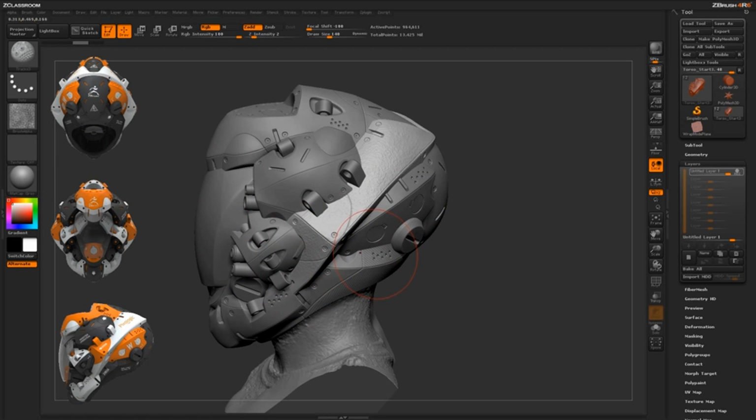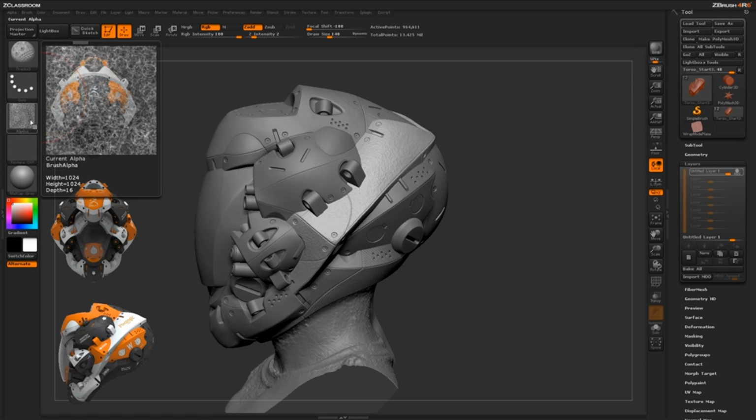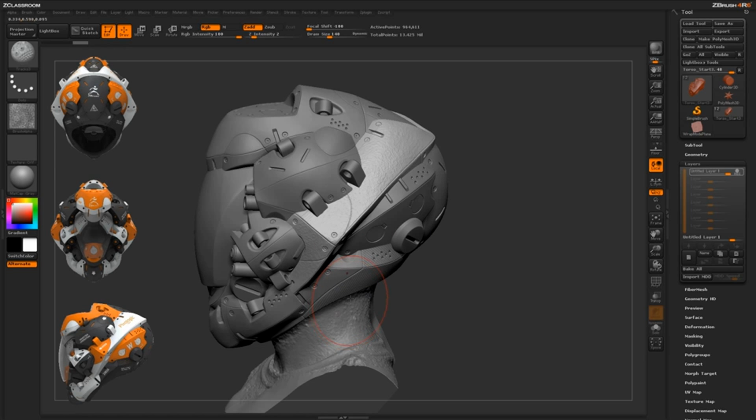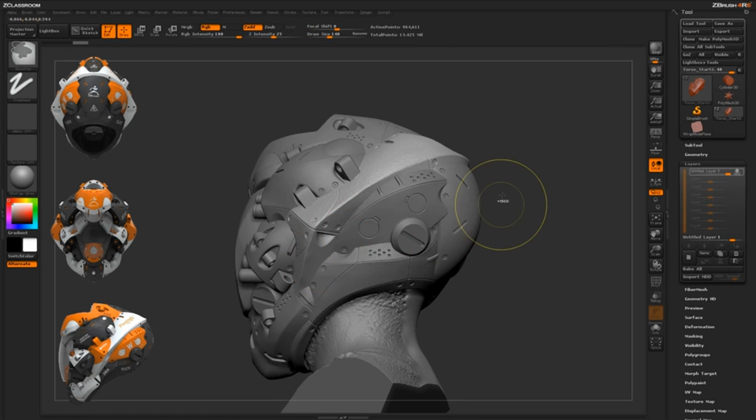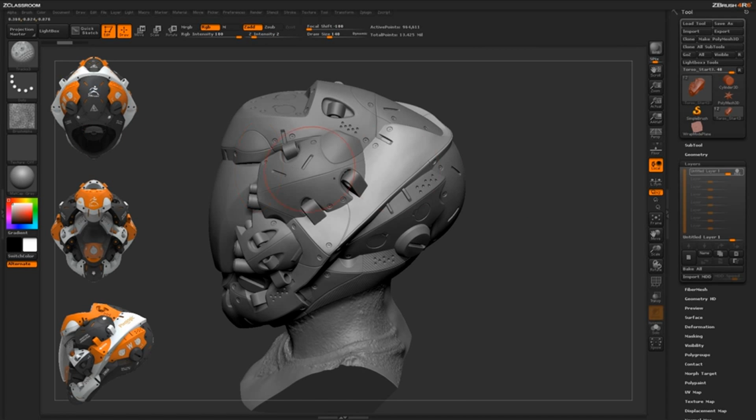So this process here is great for using on straps or other really skinny elements that you may have on your model that are going across multiple surfaces or multiple angles. So drag rectangle will often not be able to get those surfaces, but just using this tracks brush and applying that actual alpha to it is going to give you that uniform look which you want. Now another thing this tracks brush is really good for is establishing areas that may be masked out really quickly and not having to set tiling and things like that.